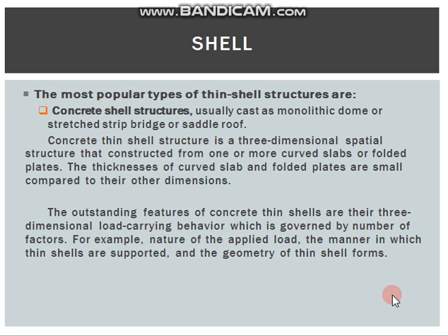A concrete thin shell structure is a three-dimensional spatial structure constructed from one or more curved slabs or folded plates. The thicknesses of the curved slabs and folded plates are small compared to their other dimensions. The outstanding feature of concrete thin shells is their three-dimensional load-carrying behavior, which is governed by a number of factors. For example, the nature of the applied load, the manner in which the thin shell is supported, and the geometry